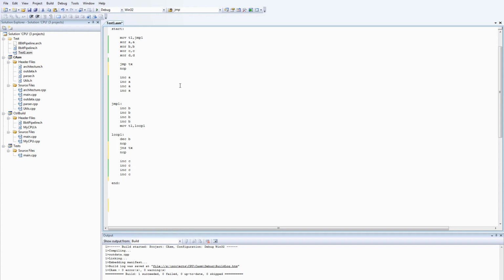So we're just going to stick the extra instructions in ourselves. Now, obviously, if I was trying to make particularly high performance code, instead of putting a NOP in, I'd try and find a productive instruction to put in that place, because executing a NOP doesn't gain us anything. But what you'll find is I'll write code initially sticking the NOPs in, and then I'll go back over it and say, well, is there anything useful I can do here? In this particular case, for example, you could do something very clever, and you could put the decrement B after the JNZ, but you can only do that if you're aware of what the 0 flag is before that start point, and of course if you're happy for that loop to always happen at least once.